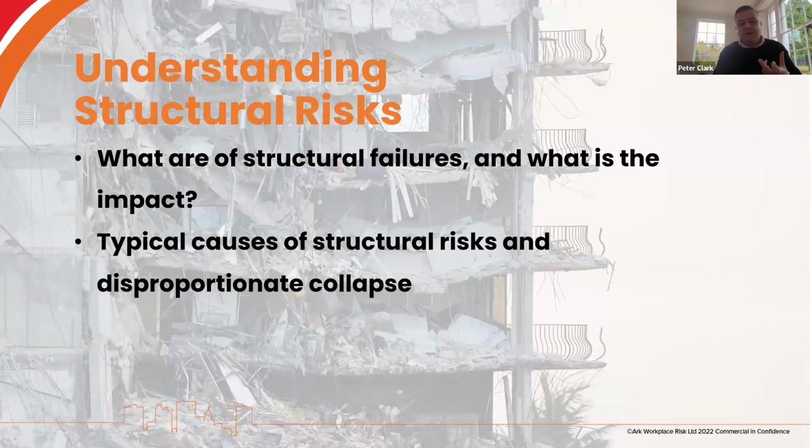So we know things are going to fail. We know that they are going to wear out. So that redundancy needs to be built in, and we need to understand how we account for that, how we account for load redistribution after a localized failure. In terms of those causes, we can look forever, but they always start with the design, unless there is a natural disaster.